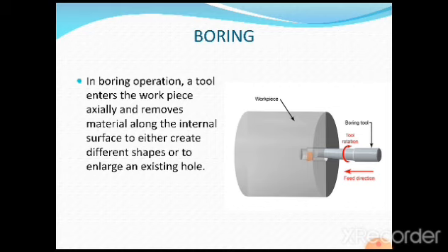So now we are coming to the boring operation. Boring operation is generally carried out after the drilling operation when we want a larger diameter hole to be produced. In boring operation, a tool enters a workpiece axially, as you are going to see the feed direction, and removes the material along the internal surface to either create different shapes or to enlarge an existing hole.